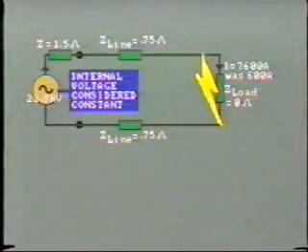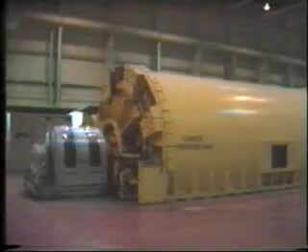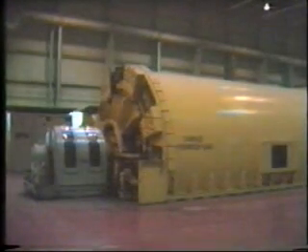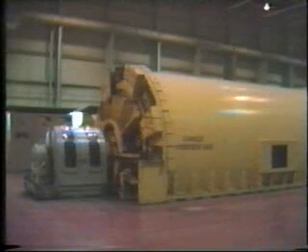When studying fault conditions, we always consider that the internal voltage of the generator remains constant. This is based on the assumption that the time interval will be extremely short before protection equipment clears the fault. In practice, it is probable that the generator automatic controls may attempt to increase generator internal voltage in order to compensate for some of the voltage drop downstream.